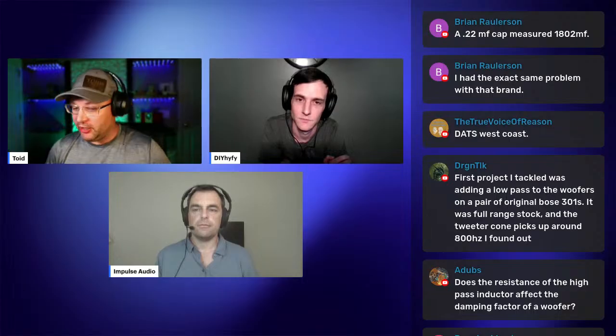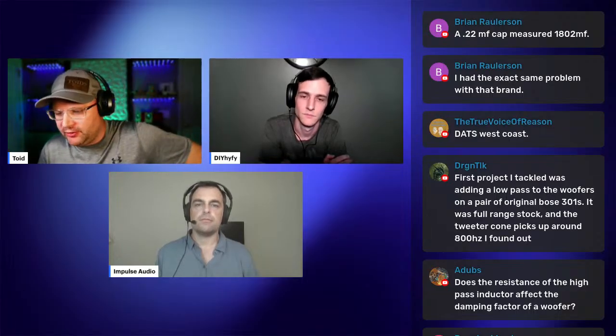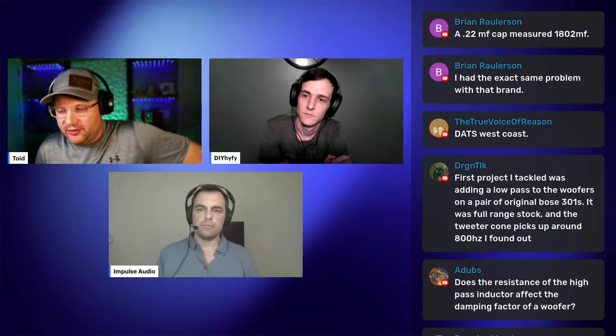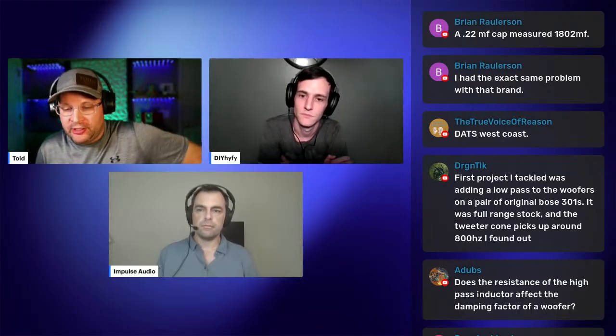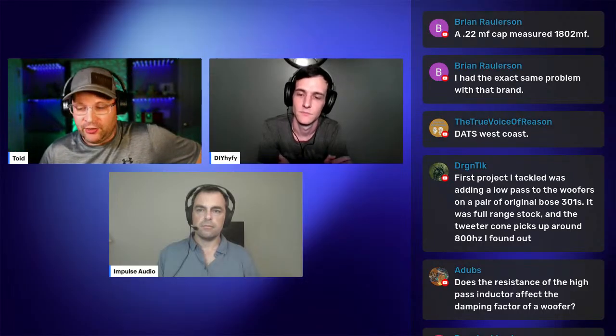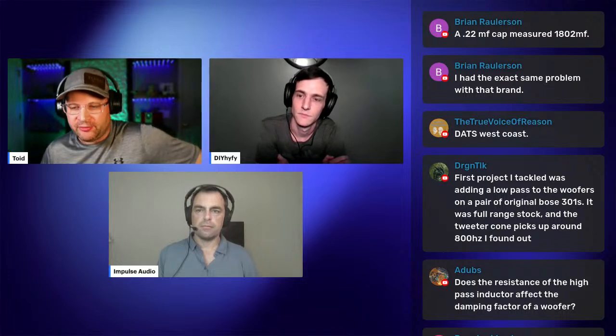active builds now, which active builds are great. We love active builds. But Ryan talks about this a lot. You've got to protect those tweeters from popping when you turn on the amplifier. It can get a low frequency pop through there that can burn out your tweeter. Next thing you know, you're smelling magical smoke that you don't want to smell.